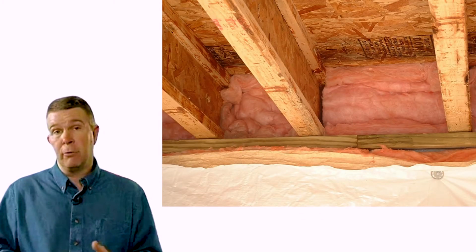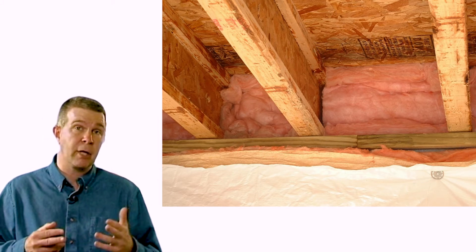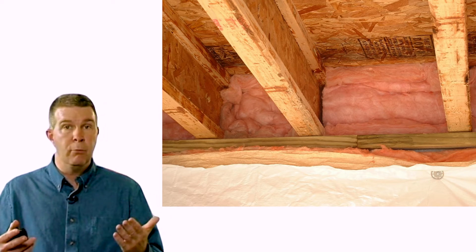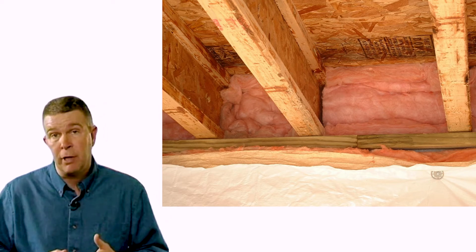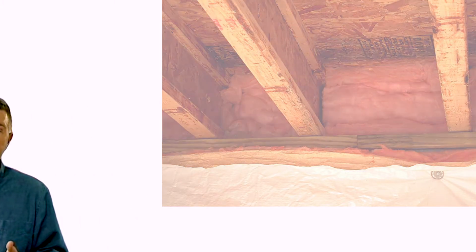If you ever want to see air move through a house, just go into a stick frame structure that's been insulated with fiberglass insulation. You can see all around the floor cubbies where air can move freely and move just as freely right through the fiberglass insulation because it doesn't stop air movement.